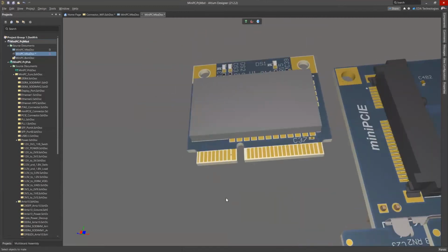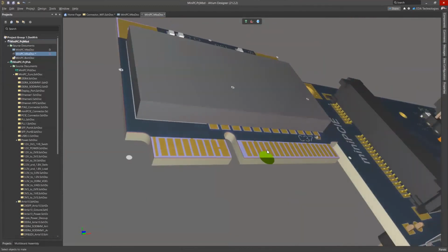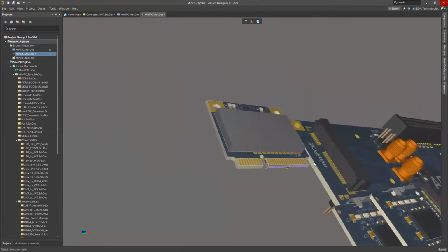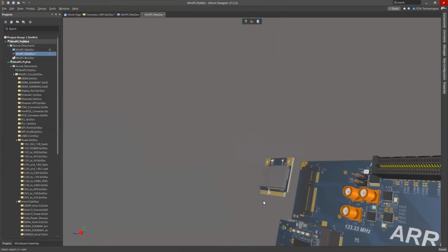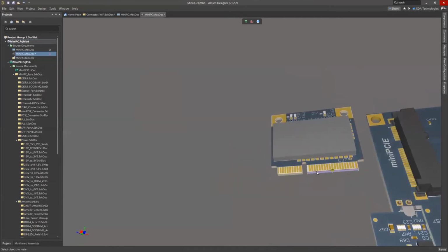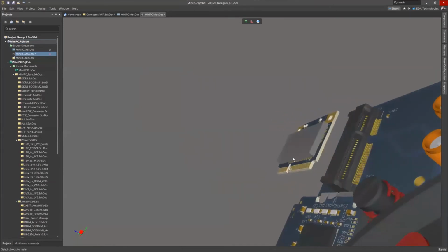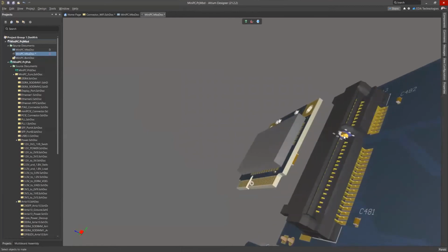So in this case, I'm going to select the object that I would like to move. In this case, it's going to be this module. I'm going to select just inside here on the center point of the little notch there. Now, I select the next object. In this case, I've selected on the long arm of the SODIMM. So I'm going to select on the inside of the step model here, the corresponding point.